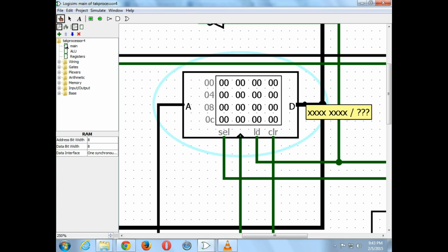But that's only an output though, right? It can serve both purposes. Okay. The data port can serve both purposes. In other words, it depends on whether your array element is on the left-hand side or the right-hand side of the equal symbol. If the array element is on the right-hand side, it is a read operation. In a read operation, the data bus is driven by the memory chip. The memory chip is now saying, hey, the content of this location is da da da da da, and hopefully the processor is paying attention so it can read that content, right?